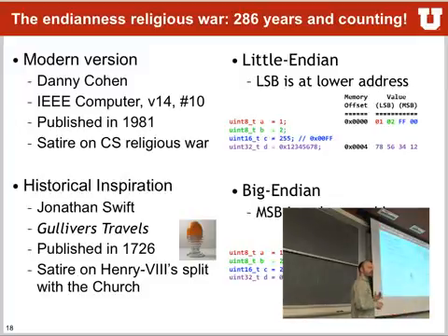Big Endian is exactly the other way around, where we have the 1, the 2, and 00FF is just 00FF. And then 1, 2, 3, 4, 5, 6, 7, 8 would be stored in memory as 1, 2, 3, 4, 5, 6, 7, 8. It's easier to read in memory than Little Endian, but at the end it really doesn't make that big of a difference. You really get used to flipping around the bytes very quickly.